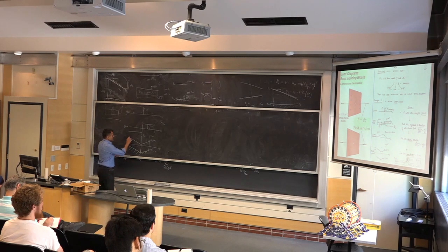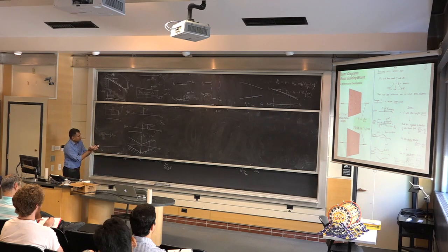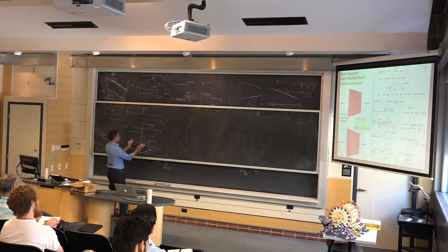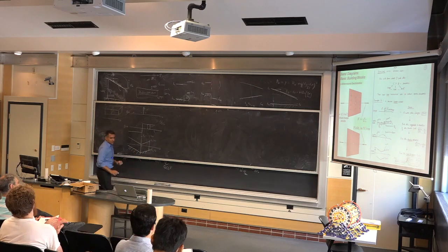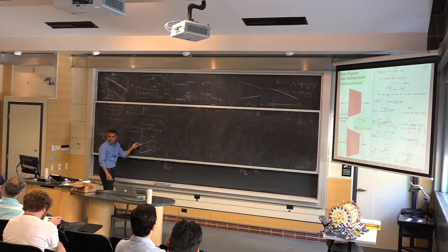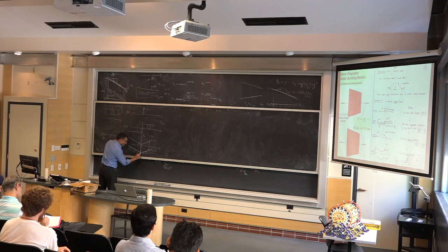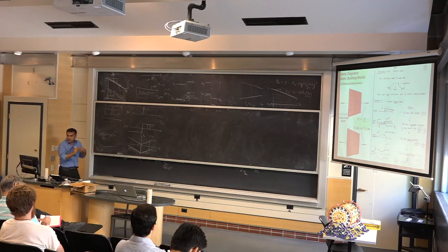So if you leave electrons here, as you can see, the electrons will kind of pile up here, and microscopically this is called a triangular quantum well, and people have used this for some interesting devices as well. So this is a triangular quantum well, if you make it very deep, and you have these quantized levels and all that sort of thing. Meaning for electrons, this is the potential they're seeing in space. For holes, as you can see, it's interesting. If you create holes, they will not stay here, they will go away. They'll get pushed out, but the electrons stay there.